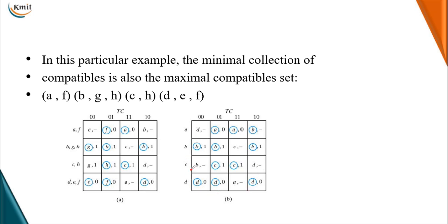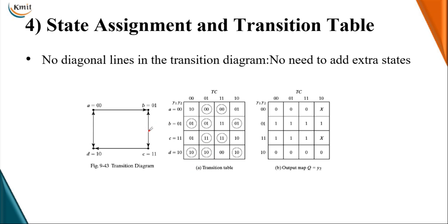So with the alphabets, we will replace A with 00, B with 01, C with 11, and D with 10, in order to avoid logical race. Let me assign the sequence of inputs and the present state in binary, with one-bit change, so 00, 01, 11, 10, which have unit distance.